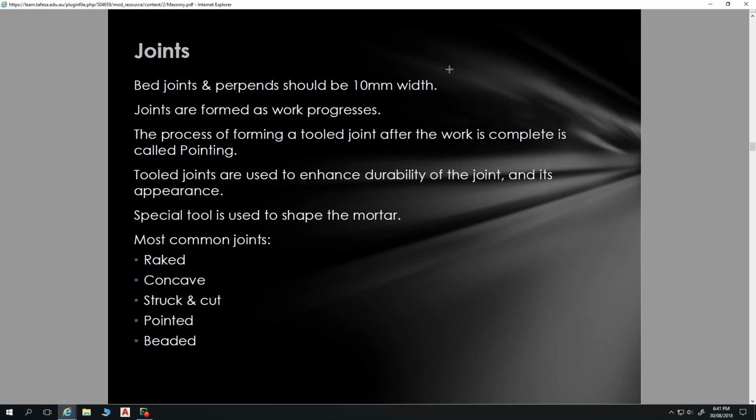You want to ensure that where you put in your door and your window, if you've got a space between your door and your window, that is in units of 240 millimeters minus 10 millimeters. So your brickwork dimensions, and I'll pull up a brickwork dimensioning chart later on as well. So buildings should always be designed, if you're using brickwork, based around brickwork dimensions.